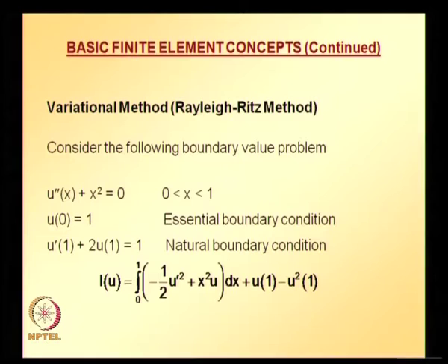One of the key concepts in finite element method is that the solution domain is divided into small parts called elements, and trial solutions are defined over these individual elements, assuming fairly lower order polynomials. For this problem, the domain is divided into m number of elements, and the length of each element can be different or it can be the same.